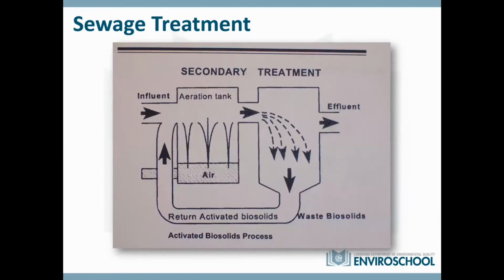Secondary treatment, again, is using biological processes. And it could be, like this one, aeration. We call it aerobic treatment. Basically, you provide air to the influent as it comes into this aeration tank. And that gets the bacteria that likes the oxygen activated. It gets them active. And as they're eating up the other bacteria, that's what's reducing all the solids and the different pathogens within that waste stream.